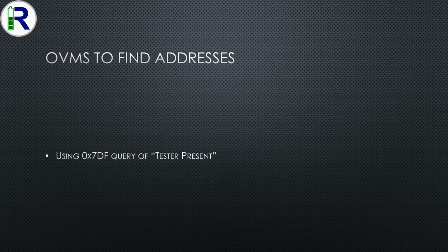So how am I using OVMS? Well, what I'm going to do is send a query to the car on the broadcast address of tester present. Every ECU should then respond to my message. So how do you do this with OVMS? And I can show you.